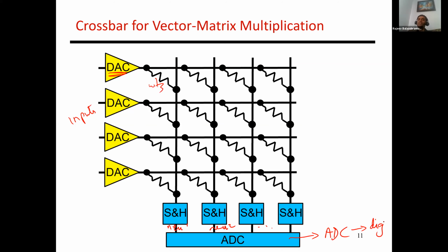So this is kind of the basic circuit saying that, if you have this grid of resistances, I can do analog dot products, and you can give me a bunch of inputs. You can encode the weights as the conductances of each of those resistors, and then I can produce the result finally, right? So there are challenges with this, which I haven't quite got to, but let me just see if there are questions, right?